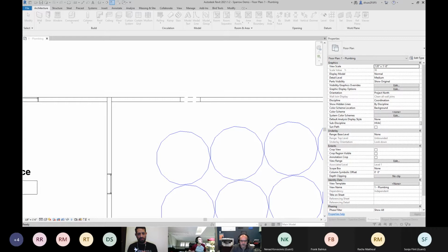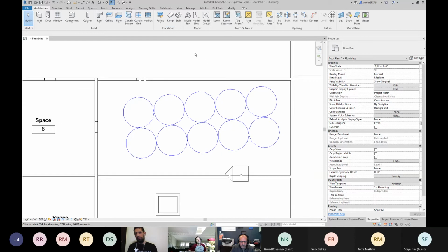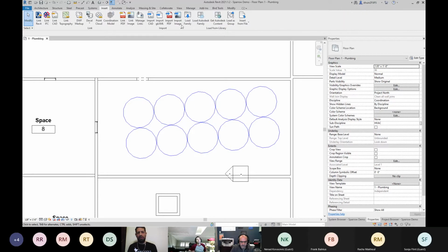I just gave a detailed one. So it's the options class, you just need to not specify the view property of that option, keep it null, and put the detail level at fine, and you get all the geometry. You can just check its type through an if statement, and when you do, you can know if it's a line or a point or a solid or a mesh. Nice.